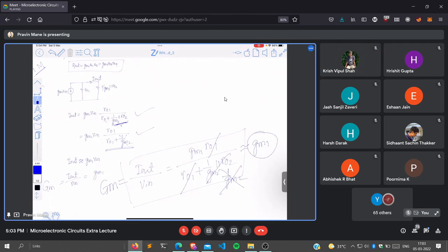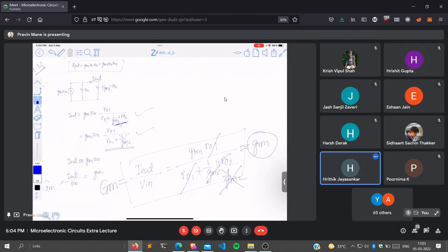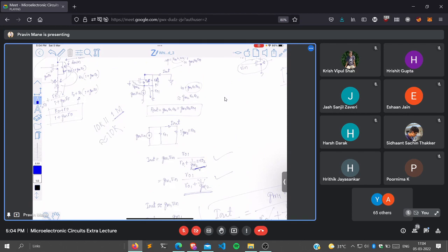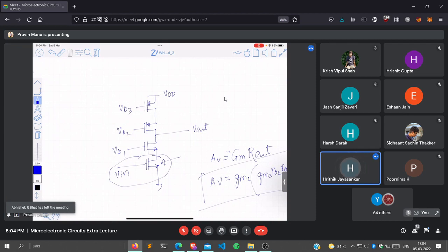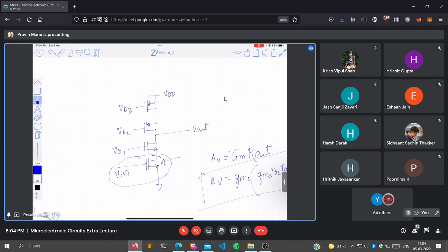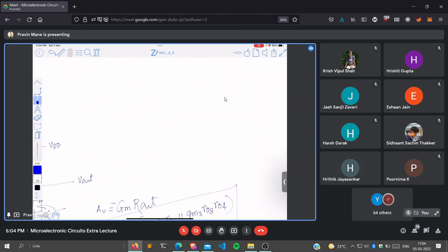Capital G. Huh? So, can you go to the cascode? Saurabh, cascode, which one? This circuit diagram. Yeah. Here, if the above two transistors are made into NMOS... It cannot be, right? NMOS cannot be used there near the VDD supply. So how will you make it? It is really difficult, because if I make them like this, so this is NMOS, right? And then the problem here is that it is really difficult to bias them.